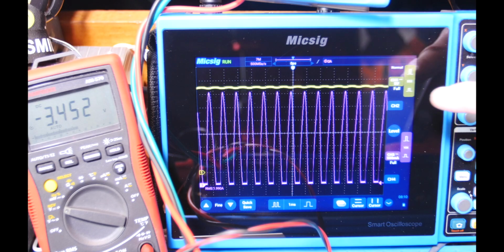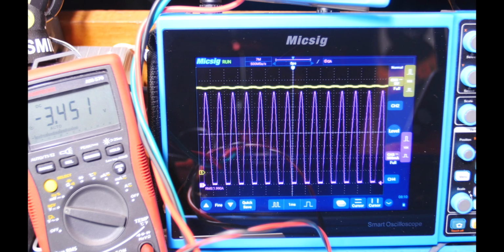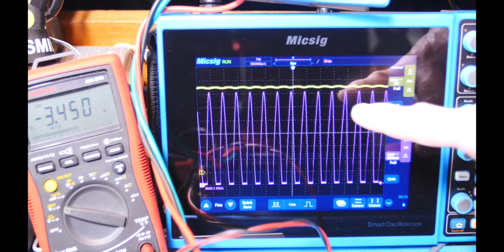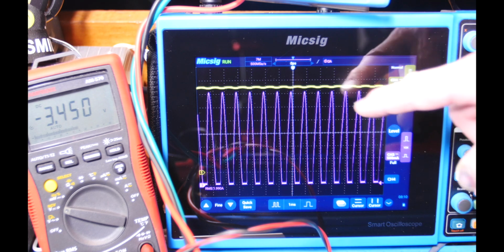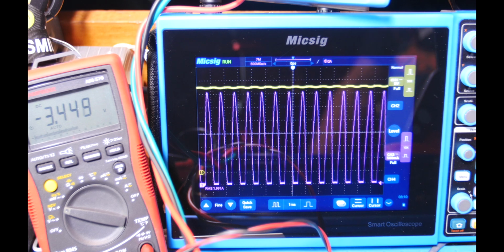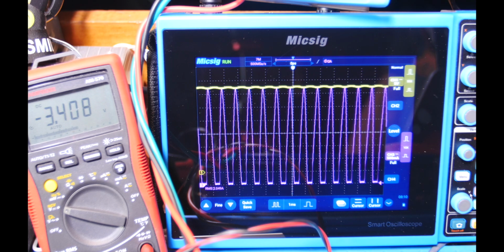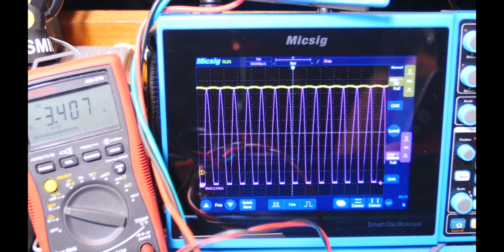All right guys, what I want to show you is the voltage ripple. I took the mix-sig differential probe and put it on the output. So we're looking at the voltage ripple on the output, and see the ripple there? It doesn't look too awfully bad. That's just before my current limit light starts going on. Then when I turn up the signal a little bit, the current limit light goes on in the power supply, but still that ripple doesn't look too bad, right?